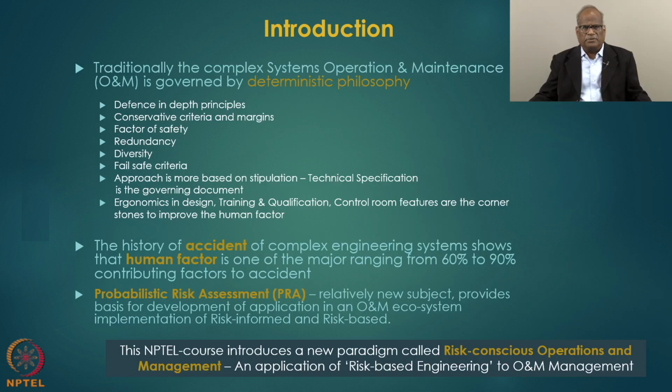Okay, so now we come to the introduction. What is the deterministic approach? I told you, it is the traditional approach for safety. Defense in depth principles mean one level of protection, second level of protection, third level of protection, and that way ensure that the likelihood of accidents is very low. Conservative criteria, okay, because as I mentioned, there is randomness with all the issues that we handle in real time. You have to be conservative. So that comes from the factor of safety. Then redundancy. As I told you, defense in depth is meant for multiple barriers of protection, so redundancy automatically comes in.